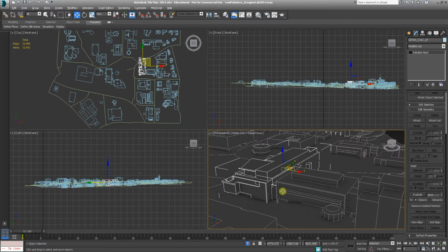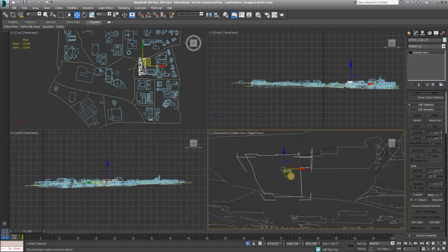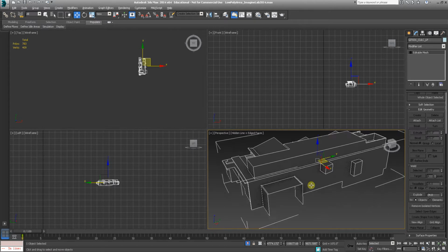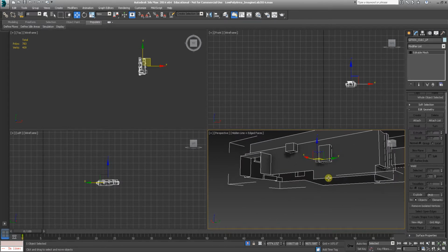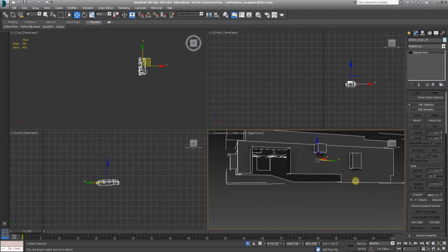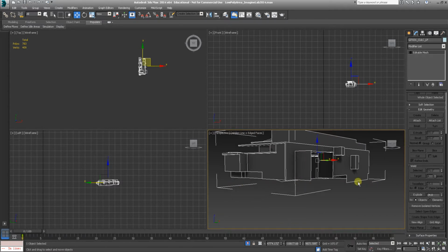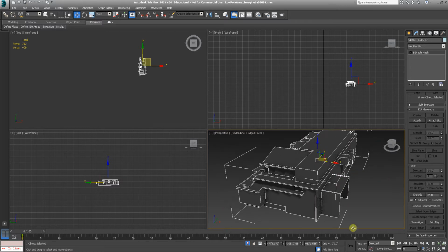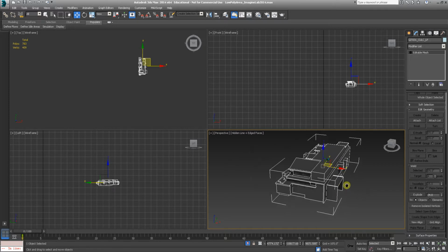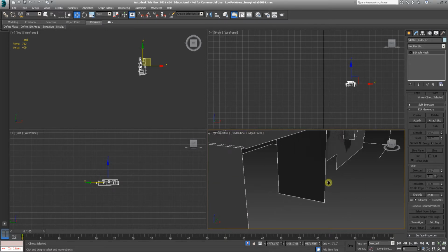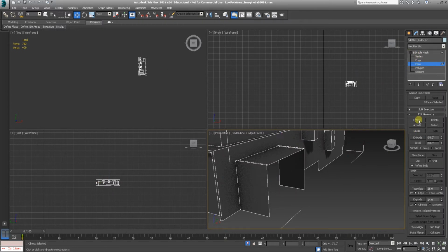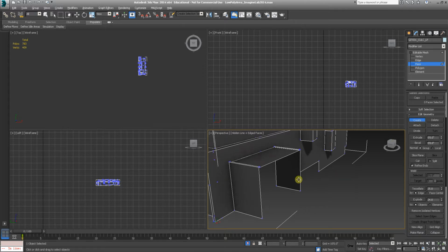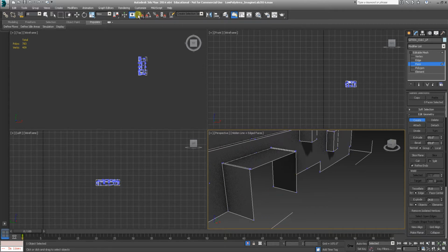So if you run into an issue where it's not capping properly, it most likely has to do with it will not cap some kind of a stepped piece of geometry like this, or it will not cap a flat surface on the bottom and a side surface here. So if it doesn't have a hole punched into it, you probably need to rebuild some faces in here. There's a bunch of ways to do that. Probably the simplest way is just to do the create face or polygon mode, and that's what snaps on.